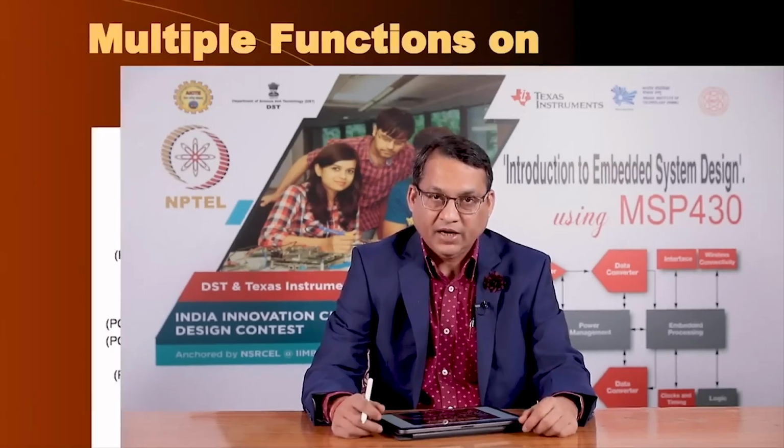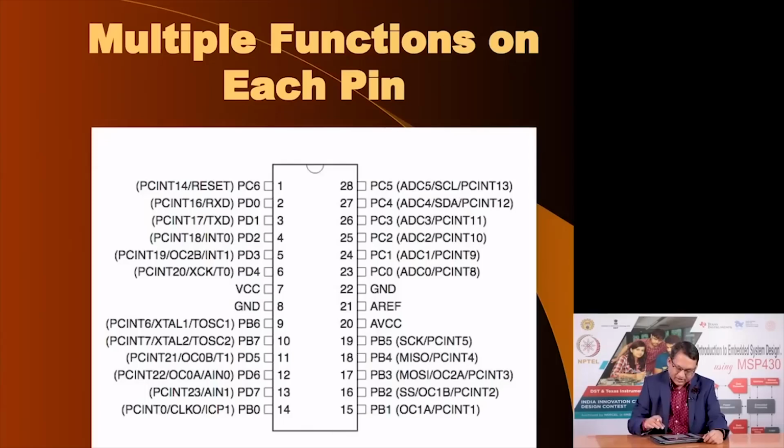Now, it may also happen that you need two functions, and unfortunately on a given microcontroller both those functions are mapped to the same pin. I can take an example. Let us look at this diagram here, and imagine that you do want to use pin number 23 because it offers you ADC channel 0.